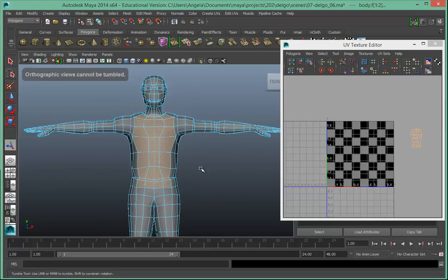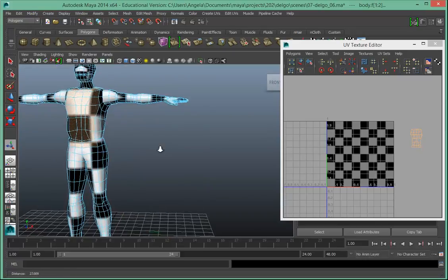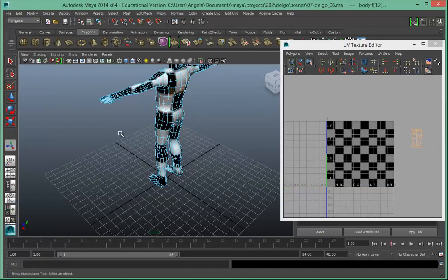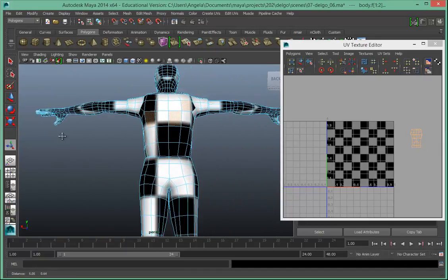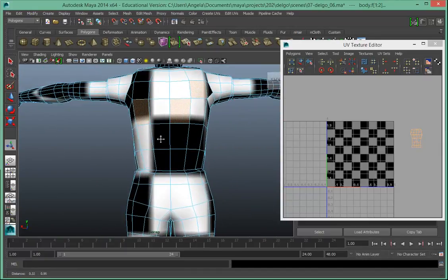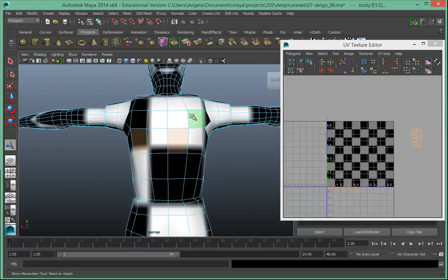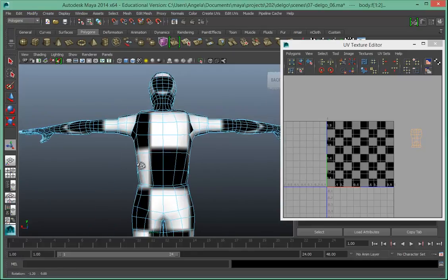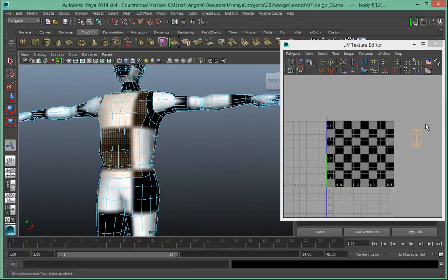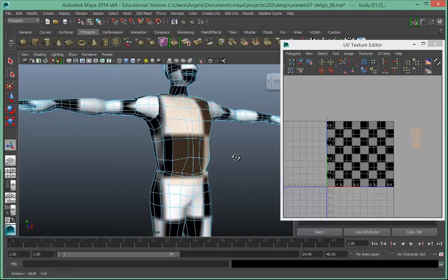Before I do that, I am going to flip over to my perspective view and make sure that no faces were selected on the back if I accidentally clicked and dragged. So if I did, in which case I did, it's shift, click, to unselect those back faces. And I'm good to go. I noticed that I had some extra ones selected over here, which is why I did that extra check.